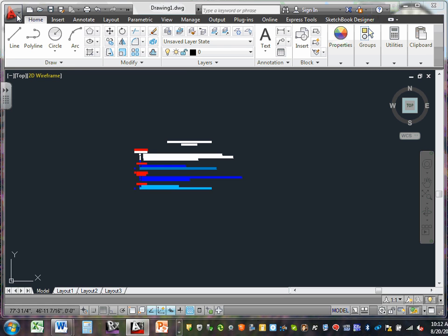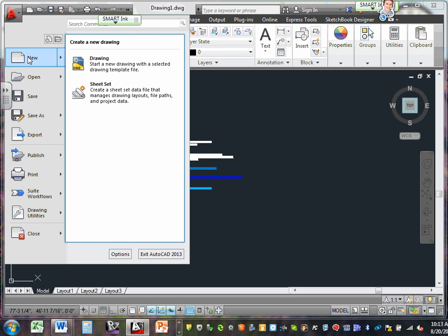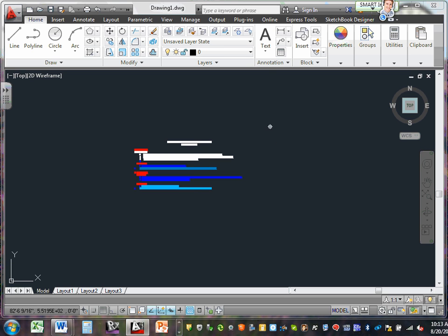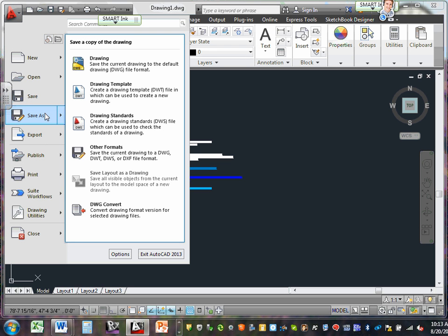But what I'd like you to do now is go to File. I'll show you a few very important things. Go right here to File. You can start a new drawing here. If you want to start a new drawing or save the drawing, you come click on that big A. Save will save what you have done. Save As will give you the option of saving it in different formats, either CAD format or others.